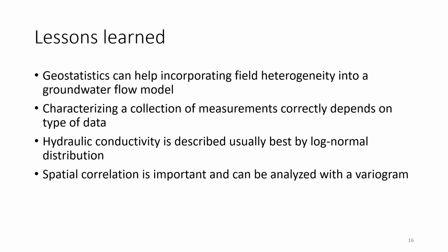So I use the scenario of contaminant transport, where I ask, well, what is the effect of macroscopic dispersion due to the heterogeneous hydraulic conductivity distribution? And you might find out that you need more information around specific regions of your modeling domain, right? Maybe around your pumping station, or maybe around your contamination site. All this is why those first estimated, randomly generated maps could help you to come up with a better solution.